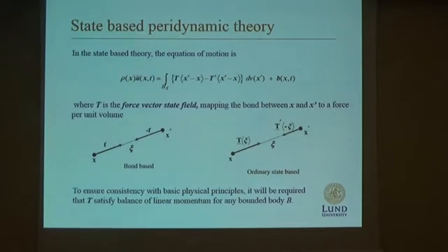And then if we go to the state-based peridynamics theory, we would like to introduce some kind of stress tensor, which we recognize from classical continuum mechanics. So T here, in peridynamics, is a force vector state field which actually maps the bond between the two particles.